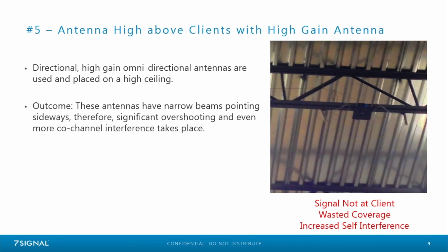And on that self-interference, remember, it's particularly true at 2.4, where we've only got 3 channels to work with in most of the world, those access points are going to be responding to all the probes of every device that walks by. So if you're in a particularly public place, they're getting sometimes hundreds of probes a minute just from people's phones and Wi-Fi enabled watches and other wearables that are out there looking for an access point to attach to. And if they hear a probe, they're going to respond. So a lot of potential for that self-interference up there where they hear each other so well.